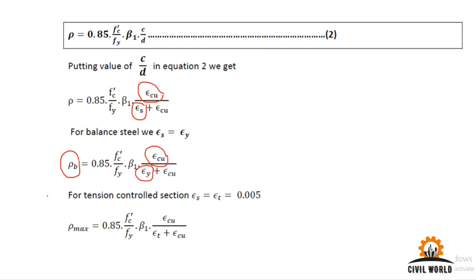Cracks will be initiated in our reinforced concrete members, and the inhabitants will have warning before the failure. There will be excessive deflections, huge cracks, and inhabitants can vacate the building before its collapse. So for that purpose, we will always be using a tension controlled section. It means that we will make sure that steel fails before concrete.